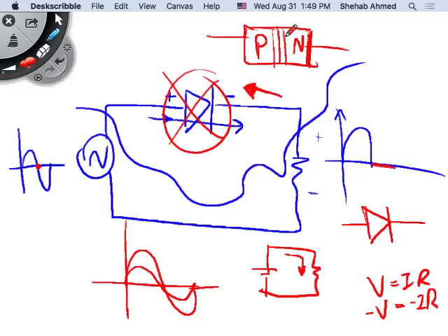We created the depletion layer, and there was some barrier, diffusion current and drift current and all of that kind of stuff. Again, we don't have to review it, but there was some barrier voltage developed, right? This barrier voltage was the one that was stopping the diffusion current from flowing, meaning the charge moving from P side to the N side, and vice versa. They were stopped by this barrier voltage.